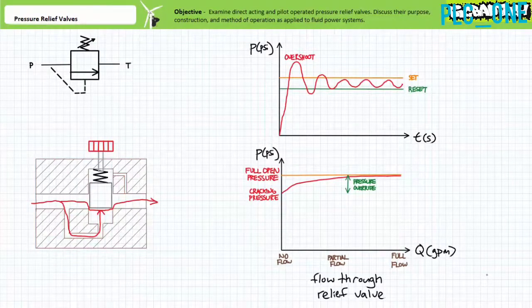Note, preset, non-adjustable pressure relief valves exist without the adjustable knob. It is incumbent upon any technician employing these types of pressure relief valves to determine if the specified fixed pressure is the cracking pressure or the full open pressure.